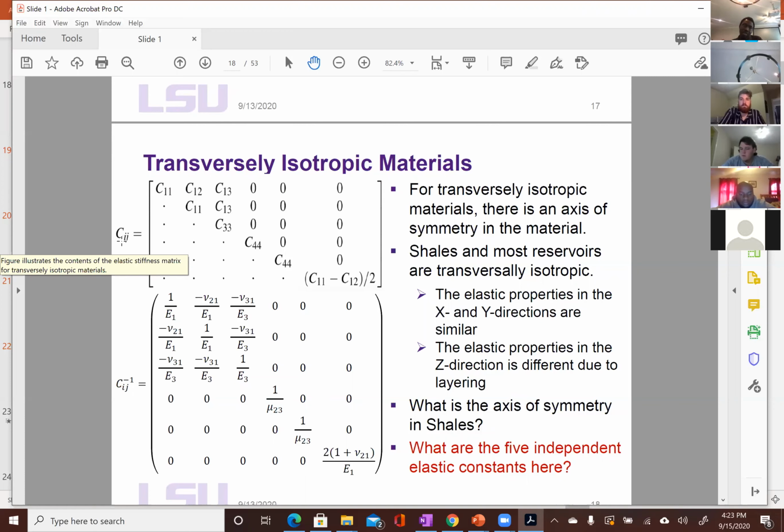And that just means maybe you're calculating epsilon. If you use Hooke's law as is, you're solving for stress given C and epsilon. Well, if you want to solve for epsilon, given stiffness matrix and stress, you can also do this with C inverse.